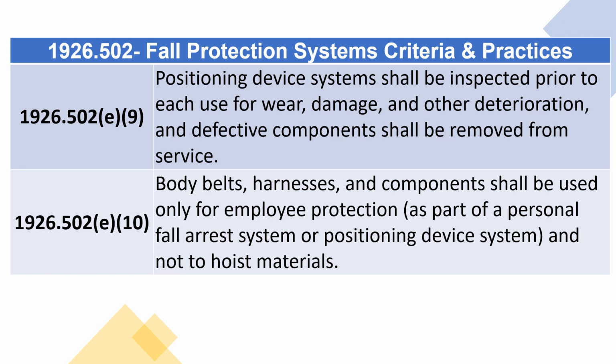1926.502(e)(9) Positioning device systems shall be inspected prior to each use for wear, damage, and other deterioration, and defective components shall be removed from service.